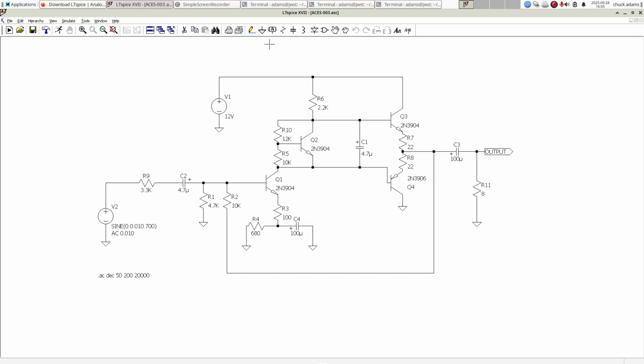So you just go and say you want a resistor. You go up here, click on resistor, and it'll bring you one. Put it wherever you want. Right click to quit, because once you put one resistor down, it'll ask you if you want to do another one, etc. Since I've already done 11 resistors over here for the circuit, it automatically numbers a new one for me. To get rid of it, I just click on it and then hit the escape key. It gives me a pair of scissors and gets rid of it.